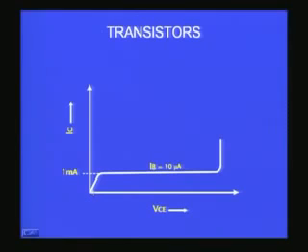So, you would find the graph will look almost flat beyond some 2 volts or 1.5 volts, and beyond some 30-40 volts, depending on the given transistor, it may even break down, and then you would get very large current flowing through the device.